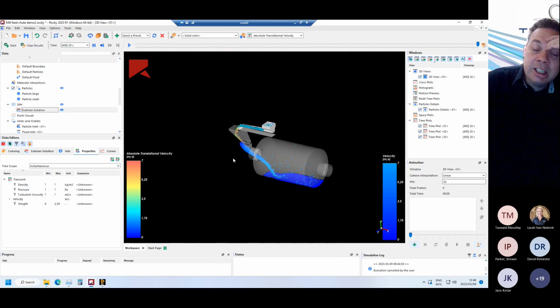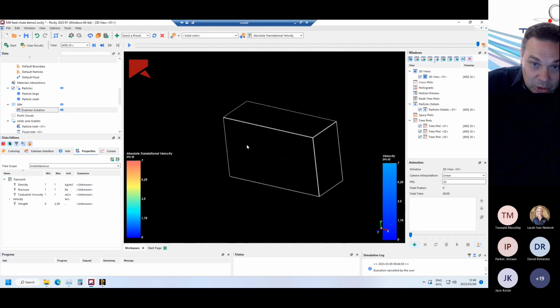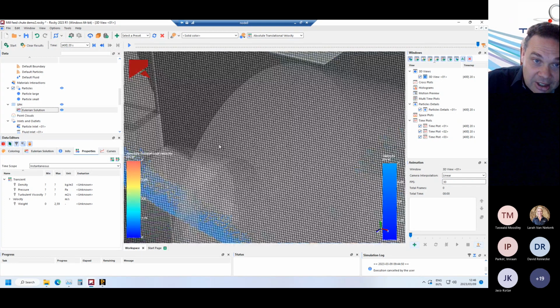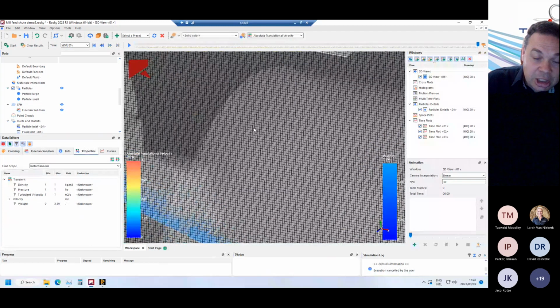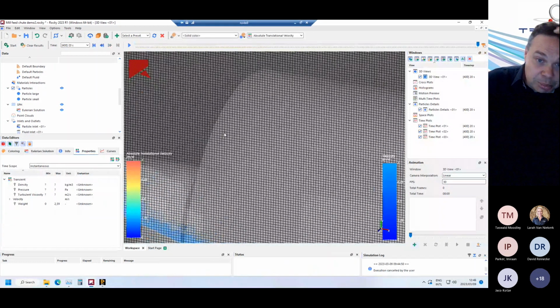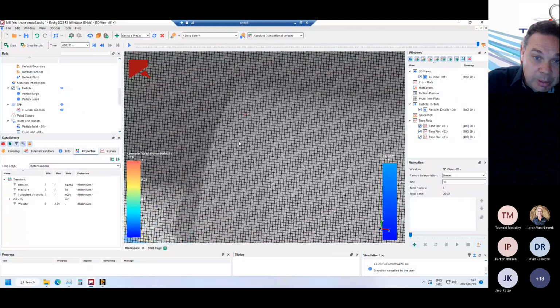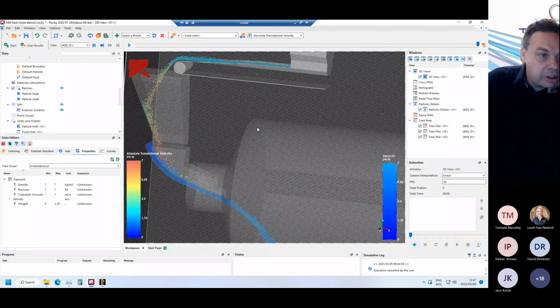And basically that then interacts with the SPH particles to extract mass information, for example. There are a lot of elements obviously in this mesh, so it does take a little bit of time to plot, but there you can see is my Eulerian mesh that's been generated in the background, and this mesh is based on that SPH size that I've specified. So each of these elements is 20 millimeters square.